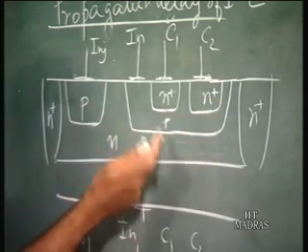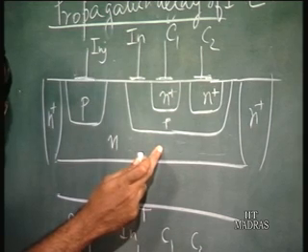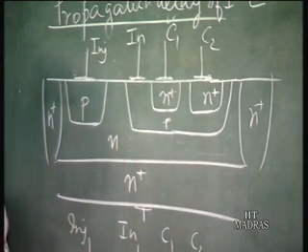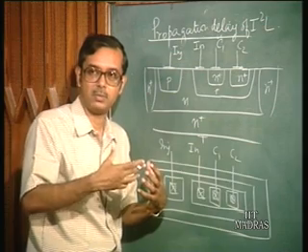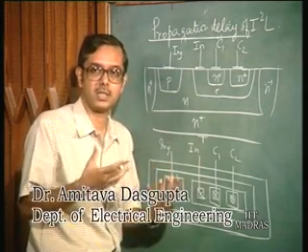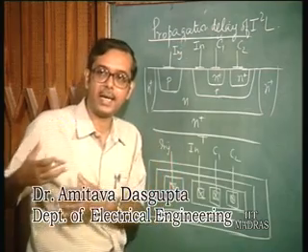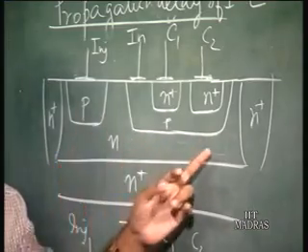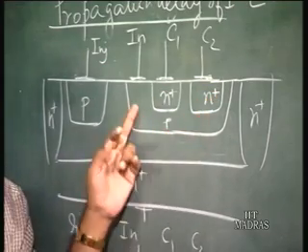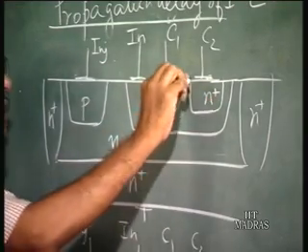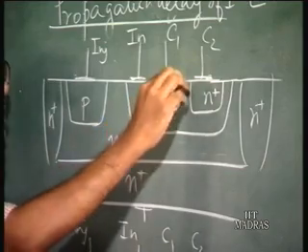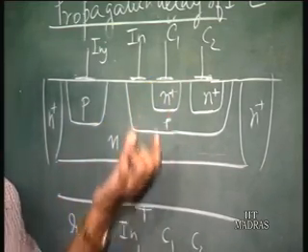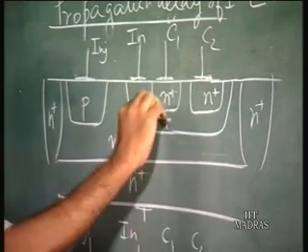So, when this base emitter junction of the NPN transistor becomes forward biased, you have stored charge in the emitter. Normally, in normal bipolar transistors, we do not talk of stored charge in the emitter because it is very heavily doped. It is proportional to Ni squared by N, so that is going to be low, but here you are going to have large charge stored. Also in the base regions, you have a lot of extrinsic base area. Extrinsic base area means the areas which are not really a part of the transistor. We call this the intrinsic area.